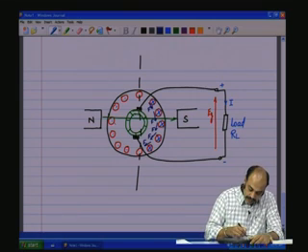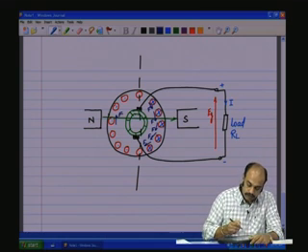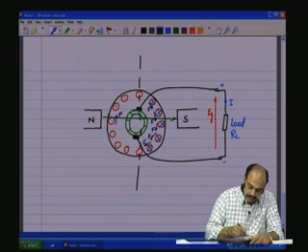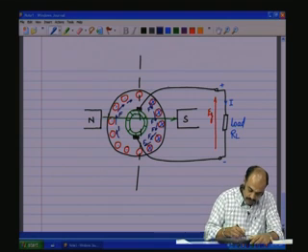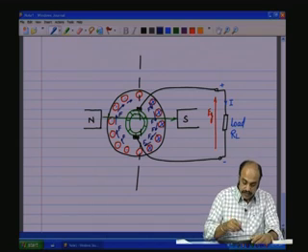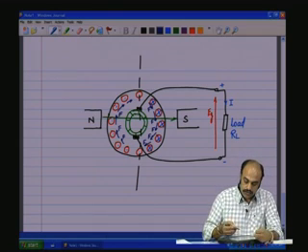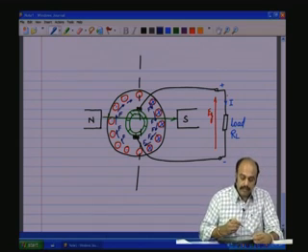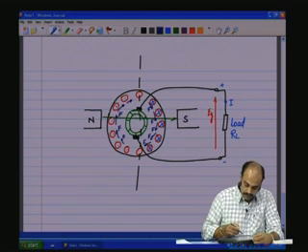Okay. Now, the current is coming out, and by again applying the right hand rule, you will see that the force will be pointing up, and therefore, they all will be aiding. The forces on each current will be aiding. So, these are the forces, the Lorentz force due to the load current which is flowing through the armature.